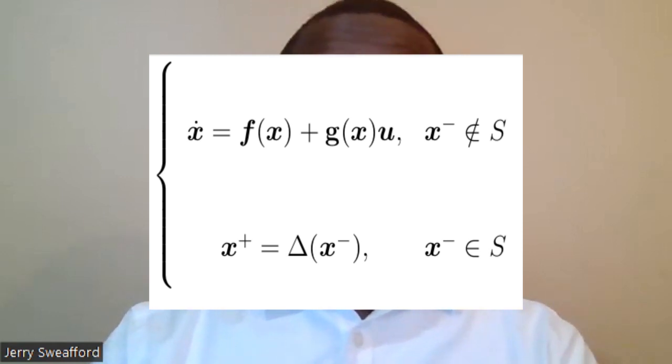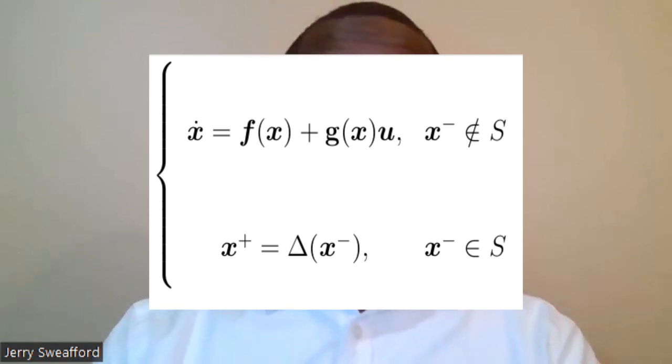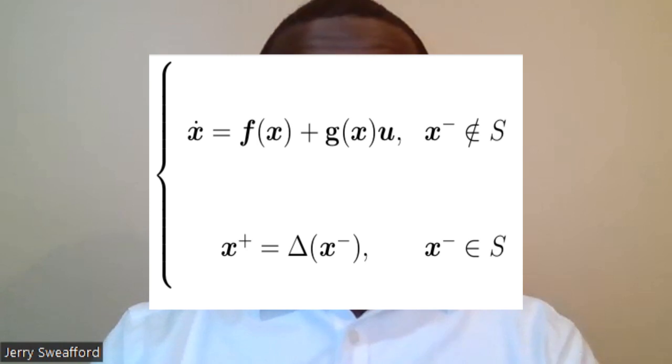time. The complete hybrid dynamic model for the 3-link planar walker is as follows. The first line describes the continuous time dynamics when the robot is in single support, and the second line shows the discontinuous state transition at impact.